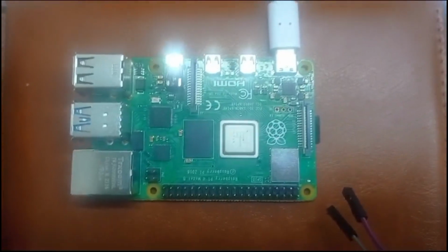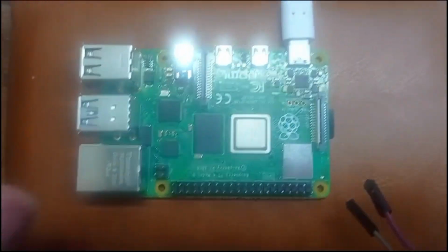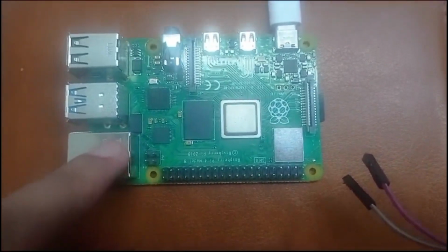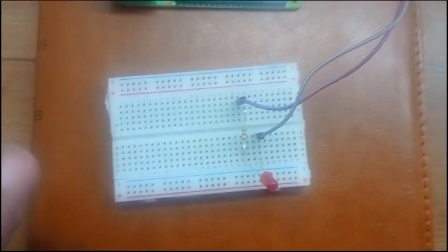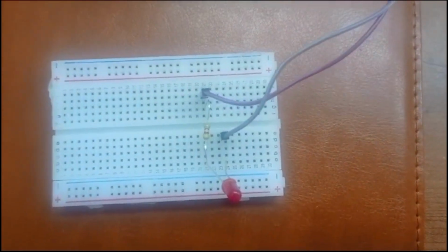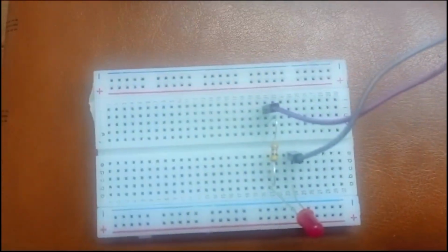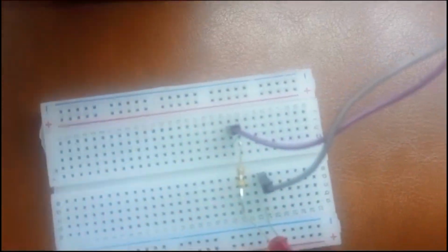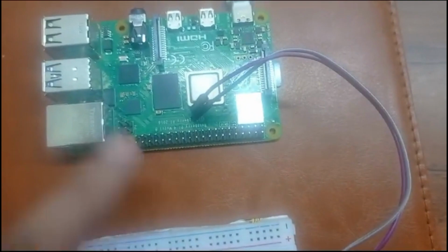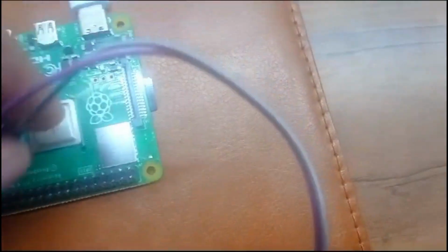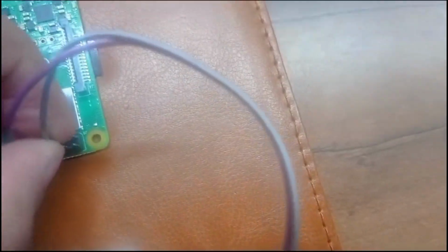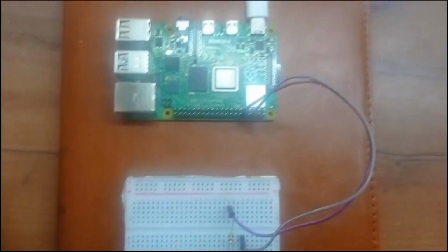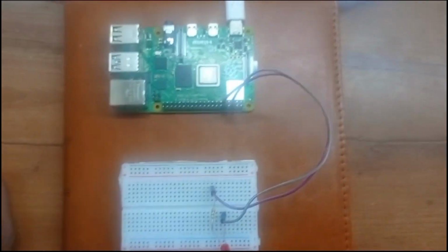This is the hardware setup of task 5.1P. In this task we were given the job of blinking an LED using the Raspberry Pi. This is the Raspberry Pi board and this is the setup for the LED blinking. Here we have used one LED and one resistor. We have used the resistor in order to prevent the hardware from burning due to overload of current. Now let's connect the LED pins to the board. We have connected the LED pin to GPIO 10 and ground, as per the code we are using. So this is the final setup for the hardware.